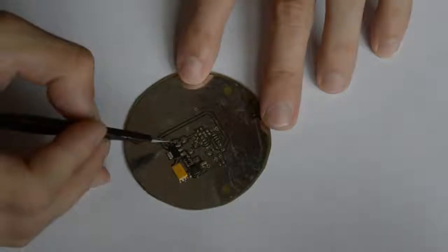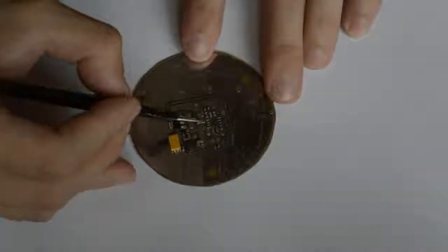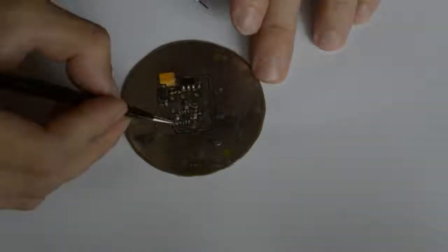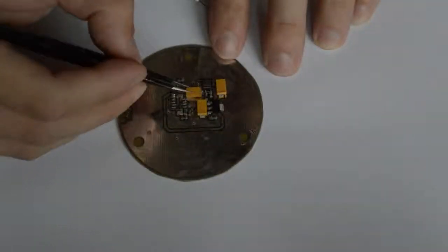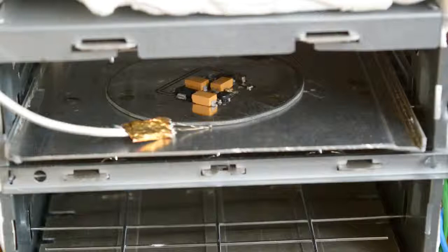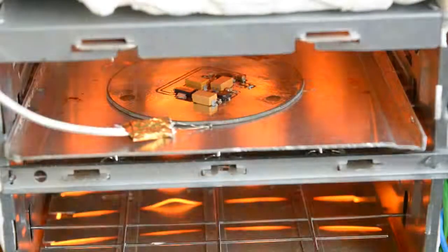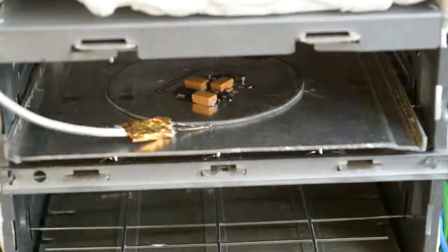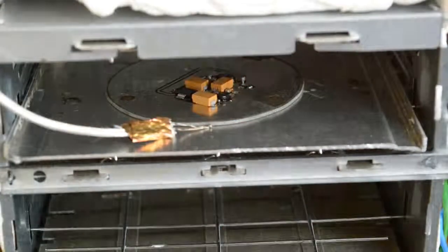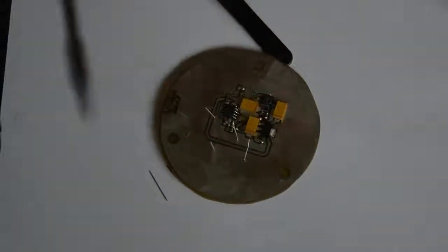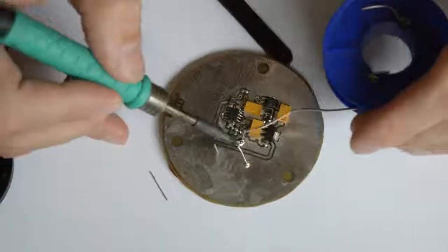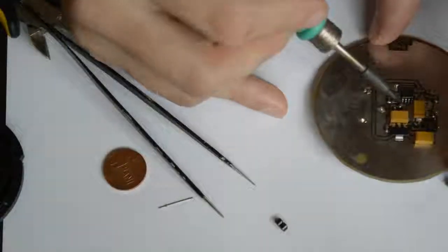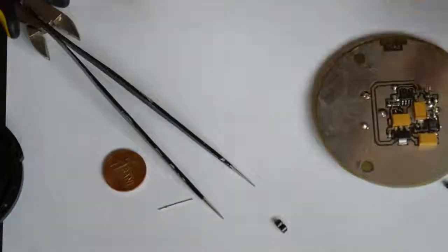The things I was looking for when I chose this particular component were the high sensitivity and the good bandwidth. Why? Well, the more sensitive it is, the less amplification is needed, and the less you amplify the useful signal, the less you amplify the unwanted noises. And regarding the bandwidth, the component I'm using has a 50 Hz to 16 kHz bandwidth. This will be able to process almost the entire audio range, and definitely the entire voice spectrum. So this particular microphone will fully satisfy my needs.